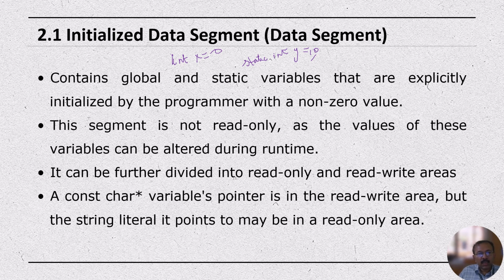Then it can also be divided further into a read-only area and a read-write area. Also, the most important thing is you are able to alter the variables during runtime. It is not a purely read-only data segment. Once you initialize x = 0, you have the liberty of modifying the value at a later point in the code. So this is the second segment, the initialized data segment.